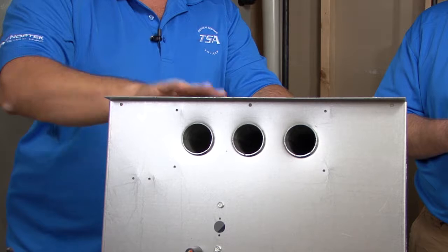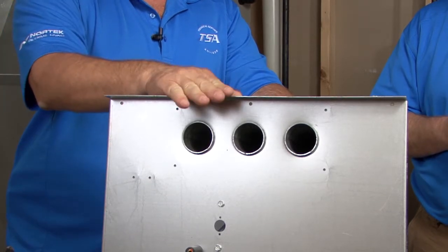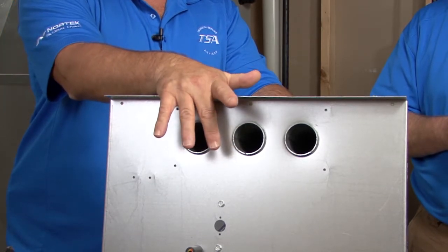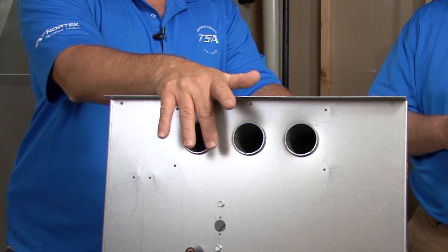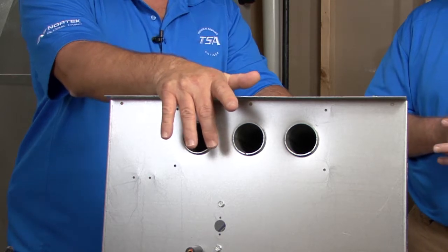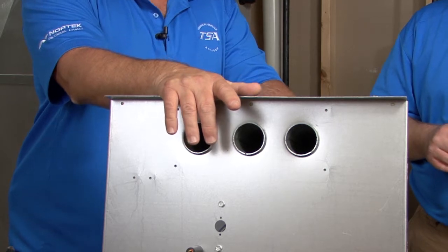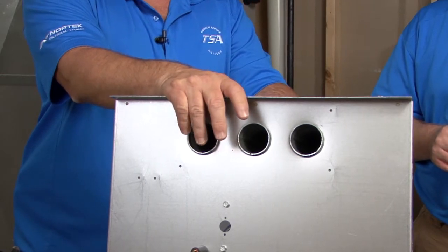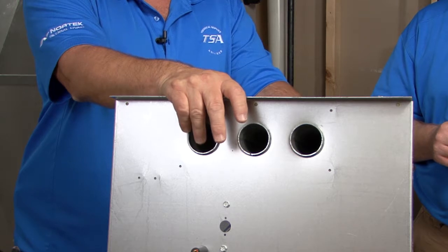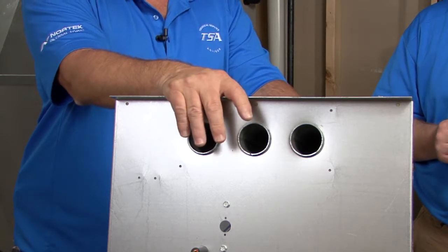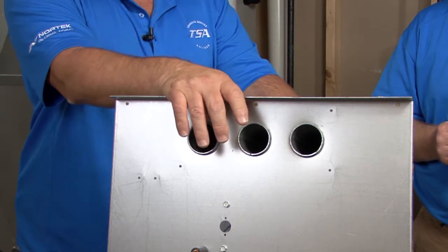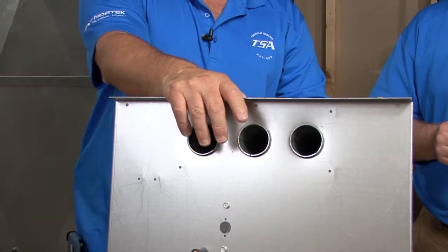So when the main blower comes on, it'd blow right through here, and your burners are right here, and you get flame disturbance. Some guys will look at it and think it's a heat exchanger problem when it really has nothing to do with the heat exchanger. We also used the smoke in those instances to prove that that's where it was leaking. It wasn't actually the heat exchanger leaking. Yeah, those are great points there.